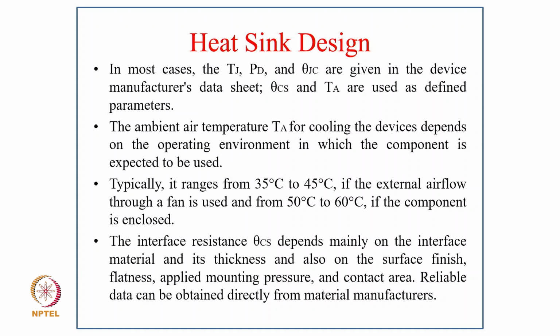In most cases, Tj, Pd and theta Jc are given in the device manufacturer data sheet, and theta Cs and Ta are user-defined parameters. The ambient air temperature Ta for cooling the device depends on the operating environment in which the component is expected to be used, and typically it ranges from 35 degrees Celsius to 45 degrees Celsius. If external airflow through a fan is used, it is from 50 degrees Celsius to 60 degrees Celsius if the component is enclosed. The interface resistance theta Cs depends mainly on the interface material and its thickness, and also on the surface finish, flatness, applied mounting pressure, and contact area.